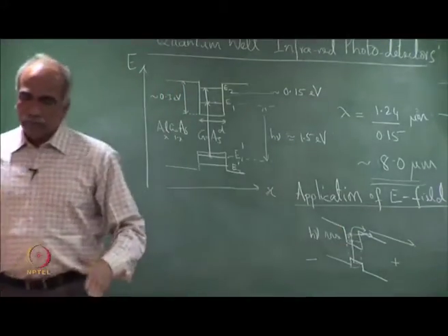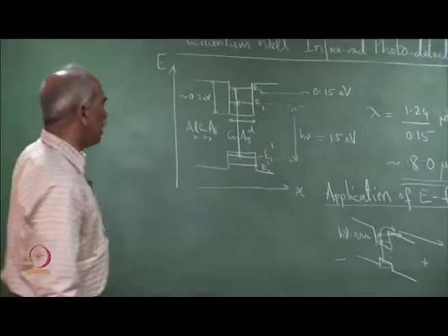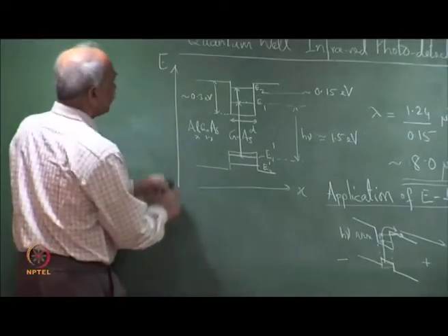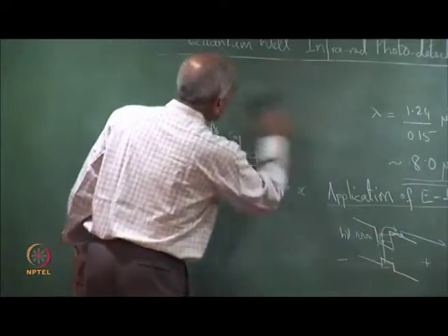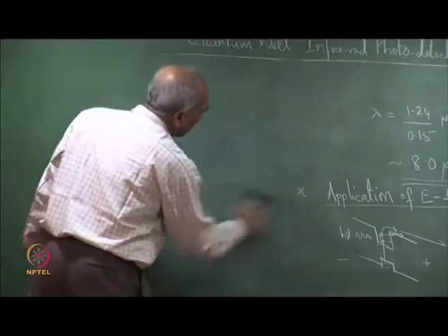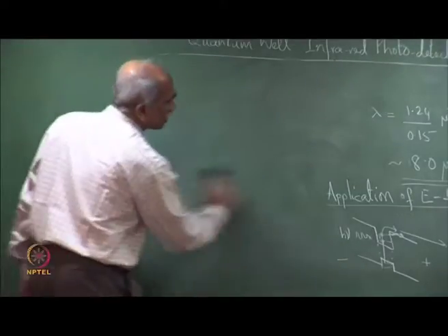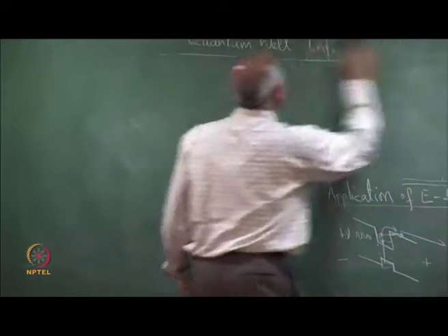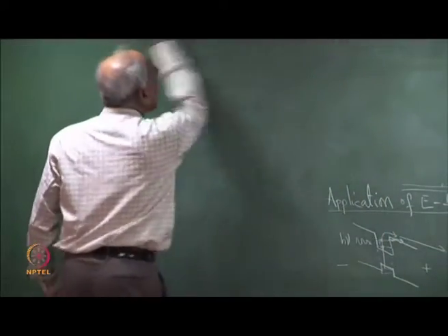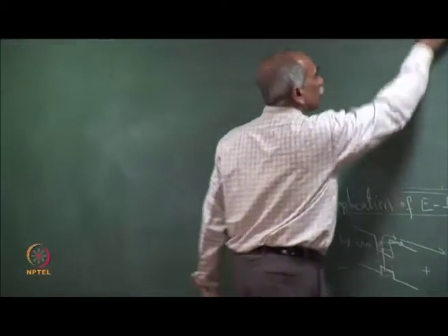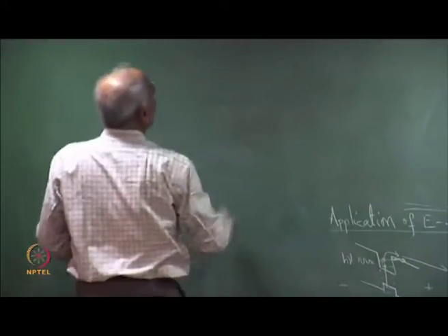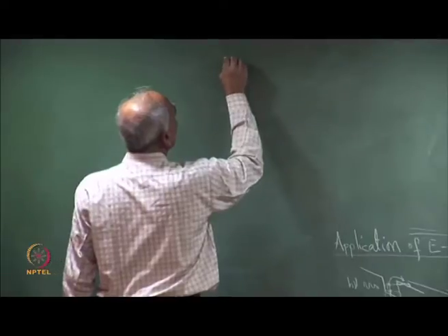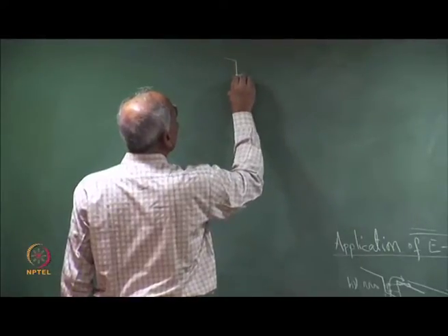Normally, one does not use a single quantum well; multiple quantum wells are used to enhance the effect. Always identical multiple quantum wells are used. We have already discussed this in the context of lasers, quantum well lasers and multiple quantum well lasers, that one uses multiple quantum wells to enhance the effect.